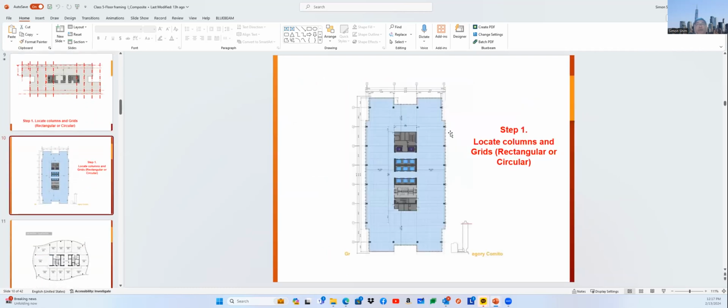Here's another, very similar example. Stairs and elevator bank, with 3 elevators side by side, keeping the overall wall width roughly 10, 10, 10, or 9, 9, 9, so about 20 to 30 feet wide, but the length depends on the overall building footprint to have enough space to serve. But you see 2 elevators and 2 stairs. Again, important: if you don't address it, you prove you are not a high-rise building specialist. So very important. The column layout is similar because of the slab layout.